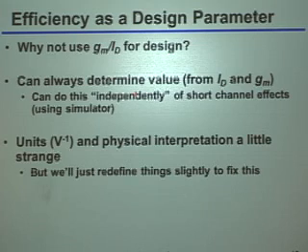You can say you can measure some IV characteristic and then try and interpolate versus some region that you assume you know what it looks like and look for the intercept. But physically, you don't know if that actually means anything or not, right? You don't actually know if the channel is actually inverted right at that voltage, or just it happened to be where you extrapolated. By the way, other people like to define threshold just as some magic current density number, right? So basically, the point there is that threshold really cannot be directly measured, right?